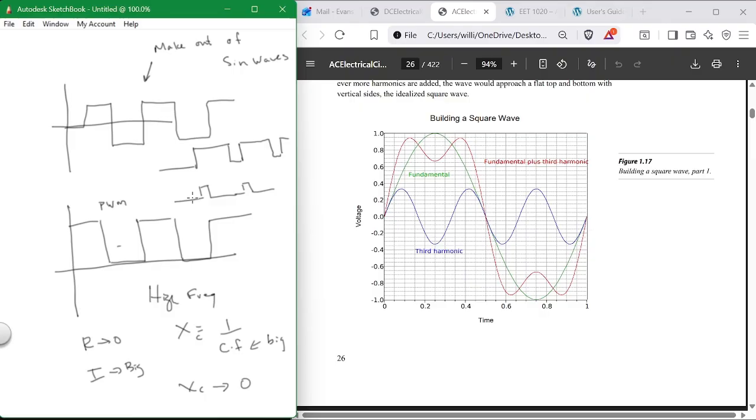An inverter. Okay? Let's get down to it. Inverters run off PWM signals. That's how you run an AC motor, with an inverter. You take an AC signal, make it a DC signal, and then you hack it up, just like that, except that you make the pieces really small. Okay? And guess what happens?